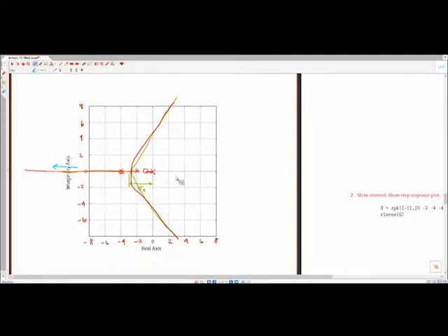We have another branch of the root locus, and it's going to have a closed loop pole associated with it. And as we see, as k increases, that pole is going to move towards the open loop 0 of the system. And then trying to tie things together between content from a few weeks ago and this specific example, what did we say about the open loop zeros and their association with closed loop zeros? This was a homework problem that we went through. It was one of the things that we talked about.